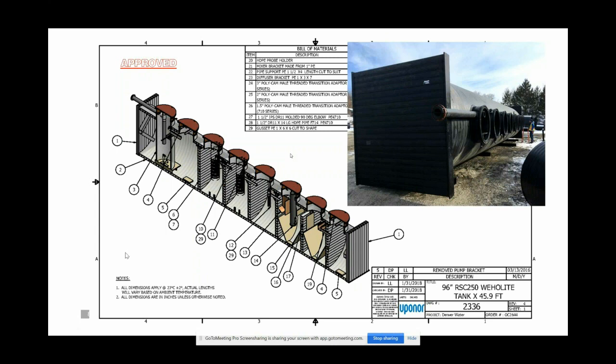It has every stage of the wastewater treatment process, and starting from left to right, I'll tell you what these different environments are. There are 8 total chambers here, and starting with this pipe coming in, that is where the influent first meets the system. It comes into a vertical trash tank where you have an aerated bar screen to remove bulk solids.